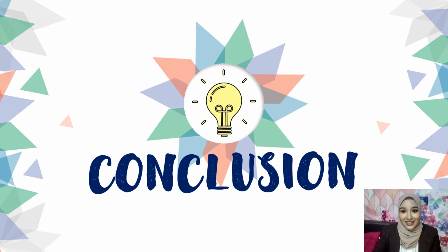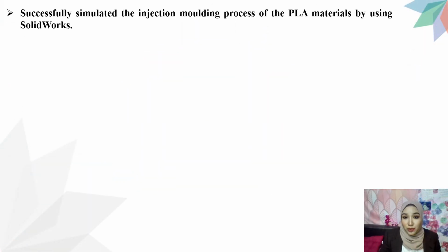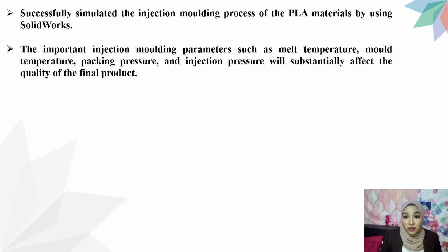Conclusions. The study has successfully simulated the injection molding process of the PLA materials by using Solidworks. The important injection molding parameters such as melt temperature, mold temperature, packing pressure, and injection pressure will substantially affect the quality of the final product.